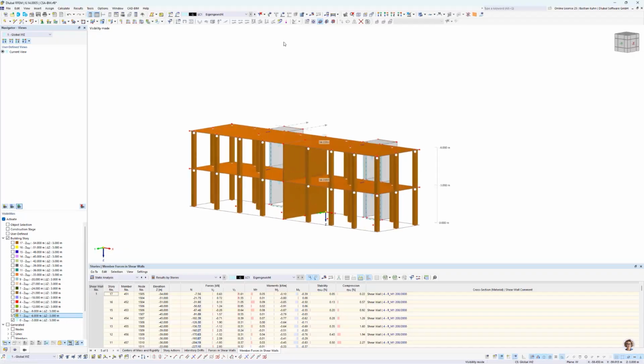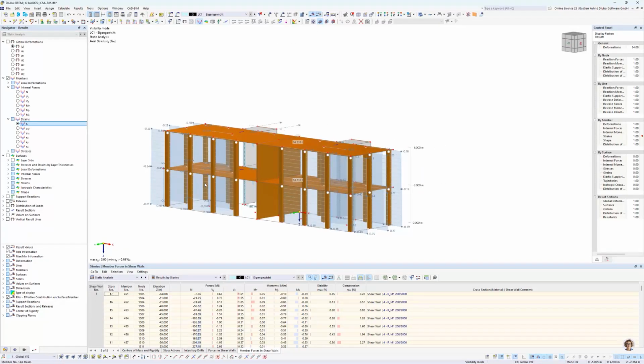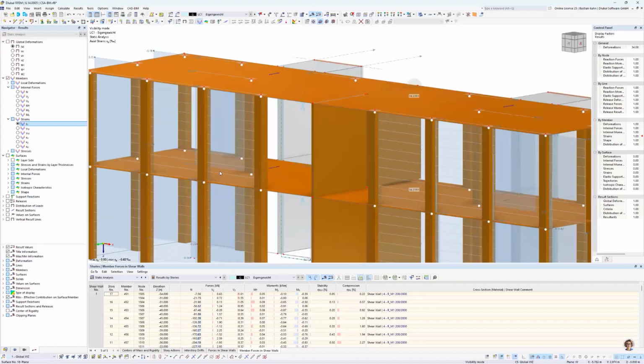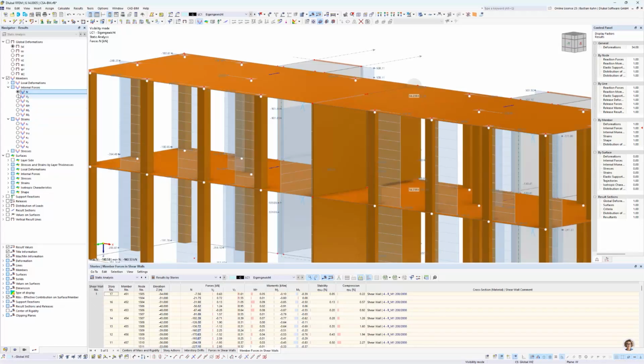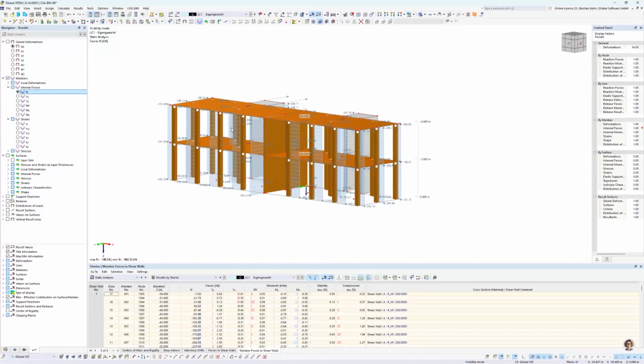There's also a strain on it, so maybe we bring the display results in here. So you see we have the strain on it, but that is the complete strain of the whole structure, so the force in the top story is moving away. So the strain is wrong, and also the normal force caused by this is wrong. And that is an effect that occurs in higher buildings.